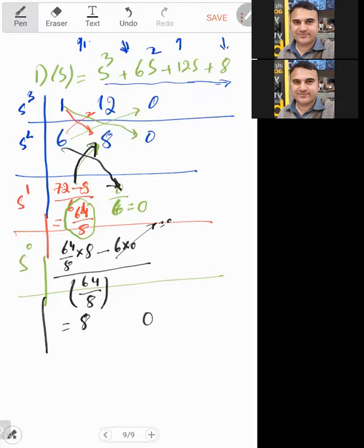The table formatting and the mathematical operations with the table are straightforward. But the most important thing is how to interpret the entries in the table. So we will be interpreting the Routh table, which is very important, because interpreting it will give you the stability information.